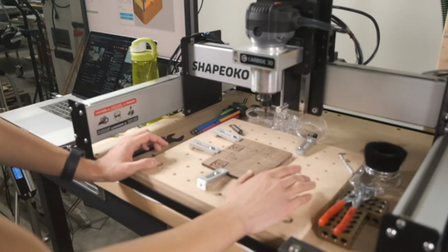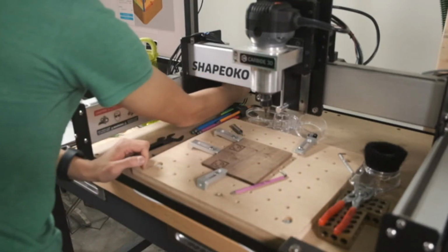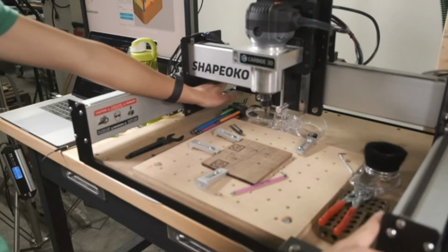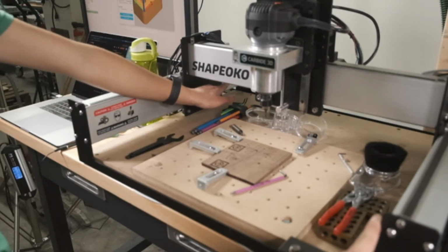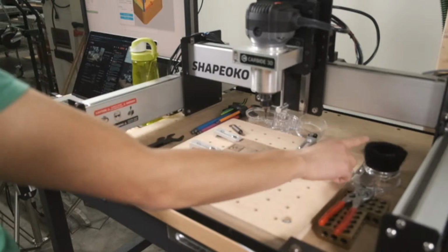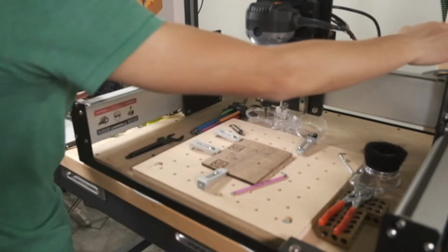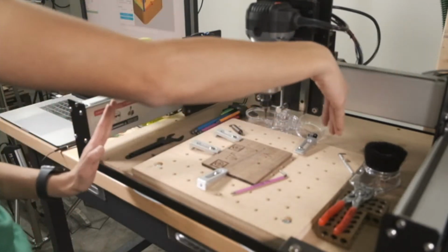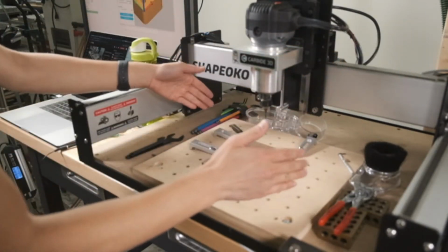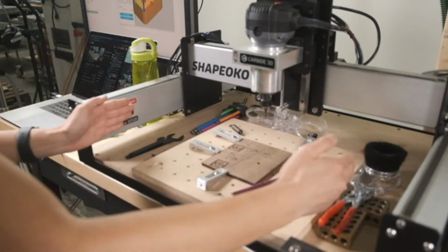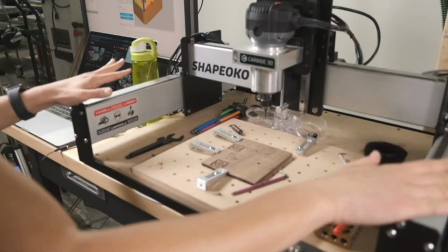What I like to do is take a tape measure and shove it into one of these corners and measure the distance across to another reference point, usually somewhere on the base frame on the front, and I'll measure corner to corner in the opposite direction, and shift these back and forth a little bit. You might have to pull them this way a little bit or this way a little bit, and once you get that set, you lock in the MDF, and that'll hold that orientation and the squareness of the frame.